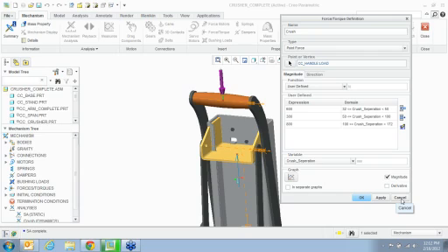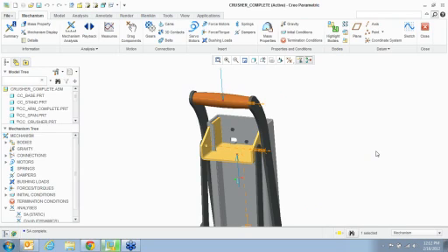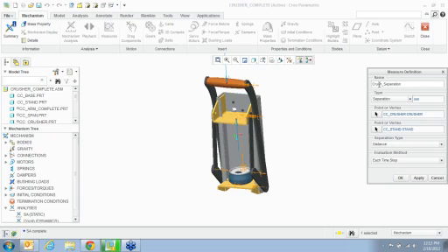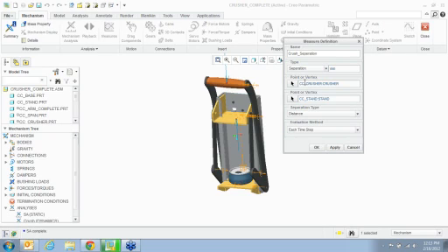and then we'll talk about the forces. So if I go to measures, see right here, I'm going to give it a name, whatever custom name we want. We say separation as a type. We select a point at the top, and we select the point at the bottom right here, and we say OK. So it's basically measuring the distance.